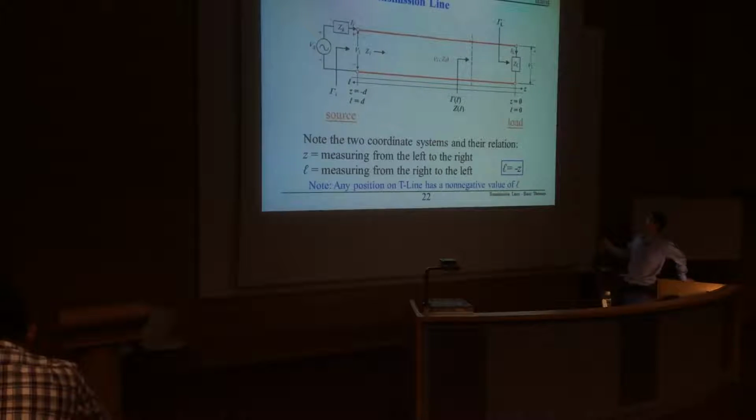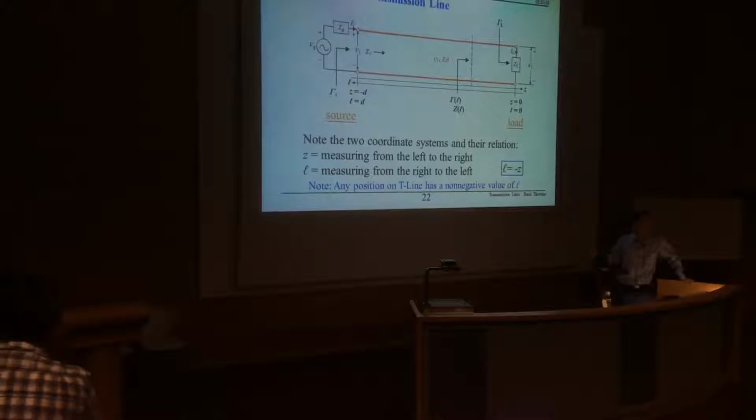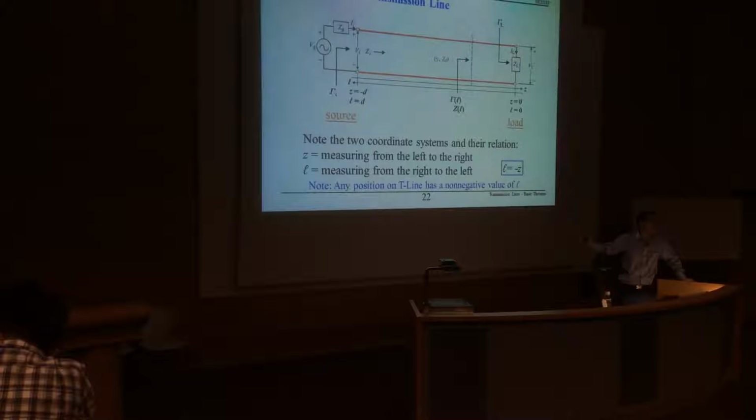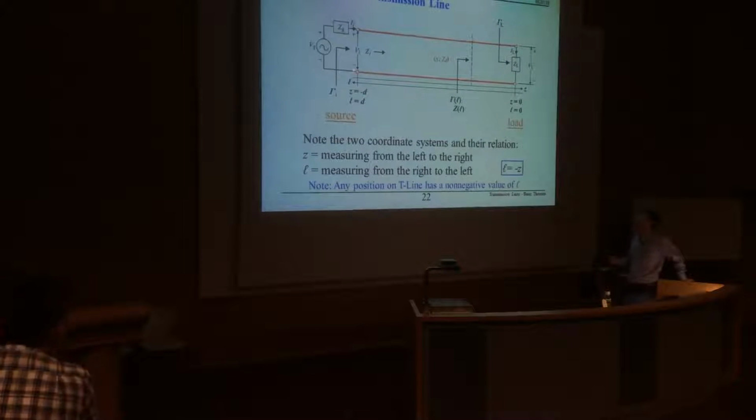At this location, maybe a different location. The reason is the reflection coefficient is a complex number. SWR is a real number. Okay? SWR along this transmission line. Since we only consider the lossless situation, along the transmission line, SWR is a constant value.